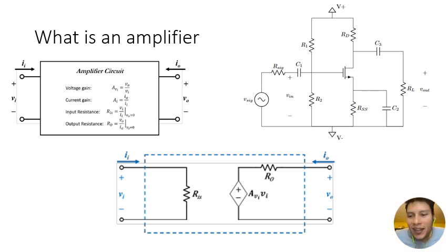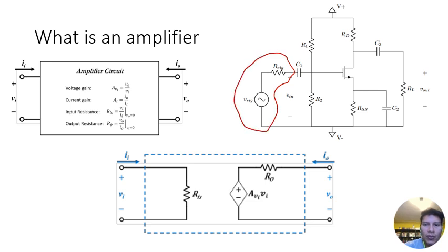Okay, but before I start analyzing these circuits and separate this into separate videos, we have to know what we're analyzing. So for all three circuits, the common drain, common gate, and common source, there's going to be a circuit model that will have an input and an output. And in this particular circuit, the model for our input is this voltage, so an ideal voltage source with a resistance in series. And then our model for our output would be this RL, or R load.